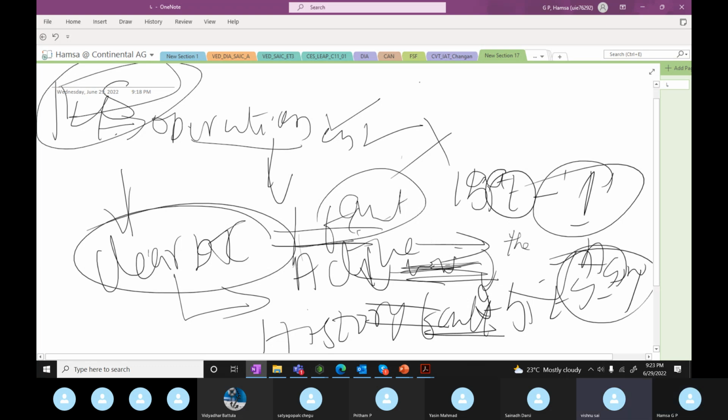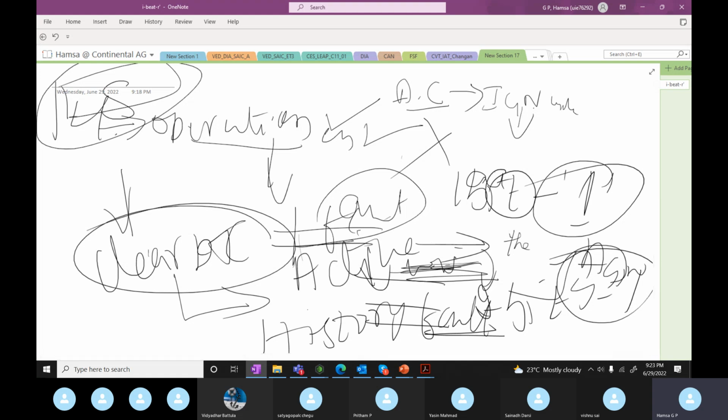The aging counter means how many times you do the ignition cycle. So today you have started your car 10 times, meaning the ignition cycle counter is 10. The ECU set the fault today that the camera is not sending input.